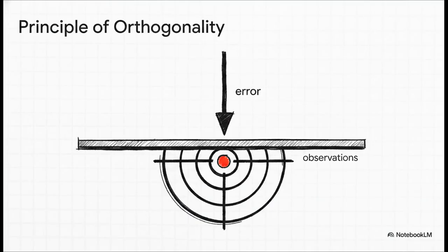filter. Picture this. We have a noisy, random signal, and we have a desired, clean signal that we desperately want to extract. Our goal is to design a filter that bridges that gap perfectly. In this context, perfect means strictly minimizing the mean square error, minimizing the expected value of the error squared. And the mathematical secret to pulling this off is the principle of orthogonality.